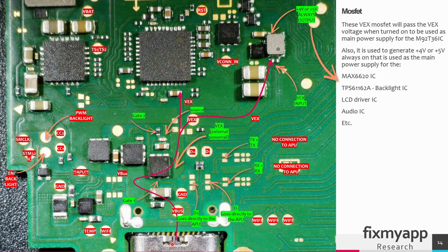Also, we have the V-bus power rail coming from the power supply. It will go eventually to the charging IC, but in this case we're going to focus on the external voltage. The V-bus will go through this fuse resistor, through this MOSFET, and it will go to the power delivery IC. It will also go to this, I think it is a voltage regulator, to deliver some voltage. So this switch controls the external voltage to enter the M92 IC and to also go to this regulator. The controlling will be done in this MOSFET. MOSFET 1 in this package, the gate 1 is controlled here and the gate 2 is controlled over here.